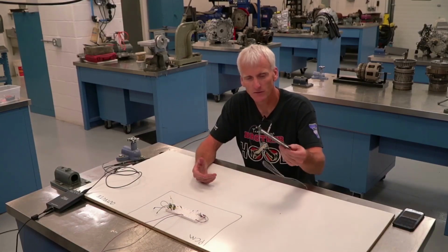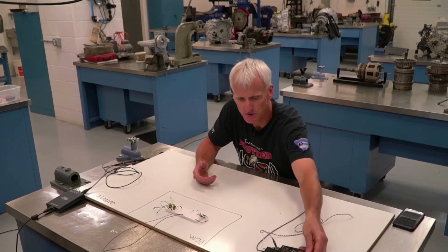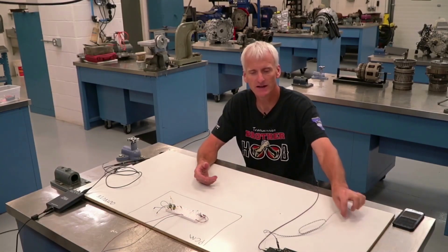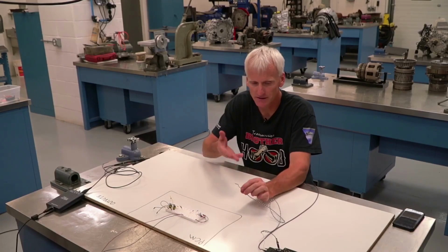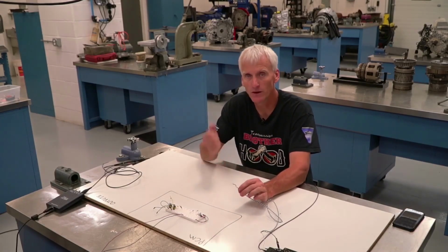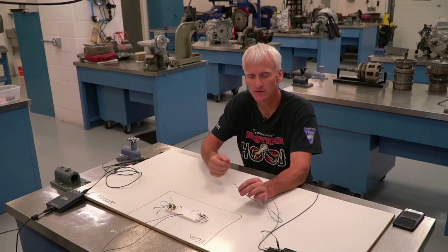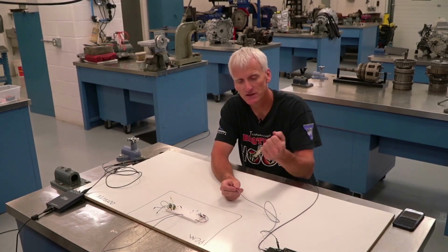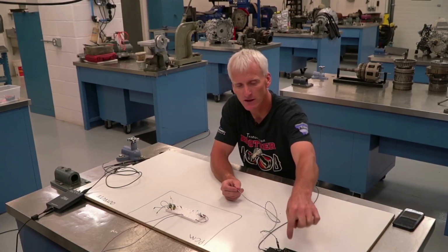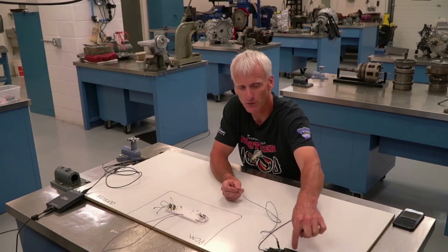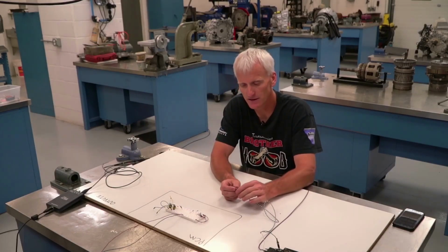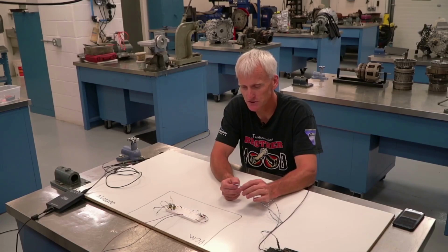So we're going to start here with this range sensor. This is a pressure switch assembly, and what it does is it provides information to the computer. In this example, it provides information on what manual valve position I'm in. If I'm in park, neutral, reverse, drive, all that stuff. And it does so by when I'm physically moving that manual valve over, I'm exposing pressure to different ports. That opens and closes those switches.